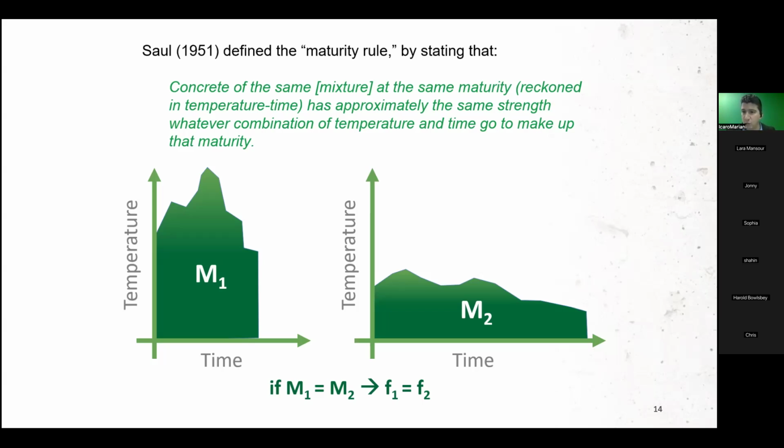And 30 feet wide, what you have is a mass effect that retains that heat for much longer, and therefore your hydration process is stronger at the early ages, and therefore you gain more strength. So it's not surface area; it's the opposite. It's that there's more mass there. I got it. You actually said that. I just didn't catch it.